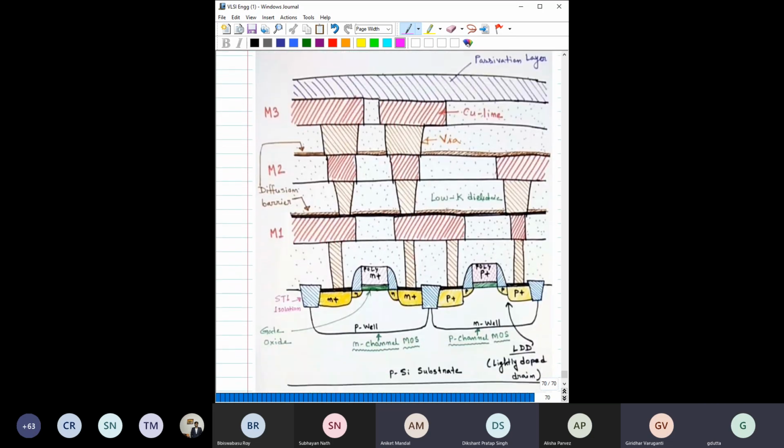Okay, to end up, we have seen a couple of techniques. MOSFET fabrication has been explicitly discussed. CMOS process flow has been explicitly discussed. Now this image would give you a final view on this. Again, I cannot write it here. So this is the NMOS channel. You can see this is P substrate. We have made P channel, we have made N channel, and here we have created this N plus, this is N minus. So this is basically with LDD structure, right? LDD structure like that.